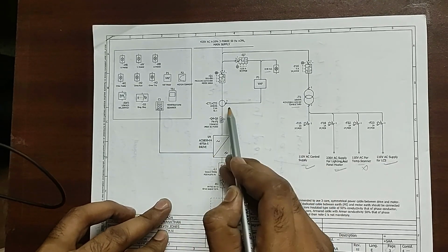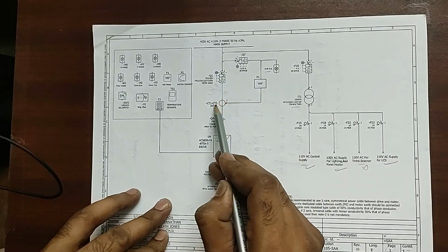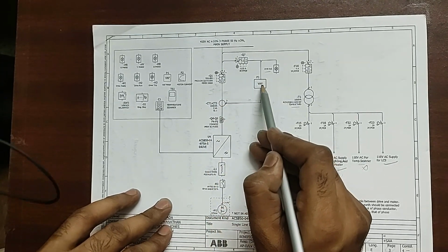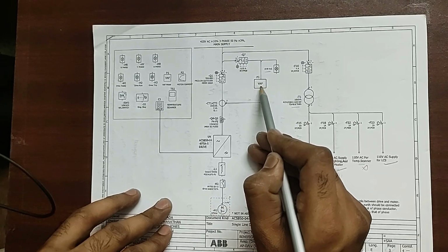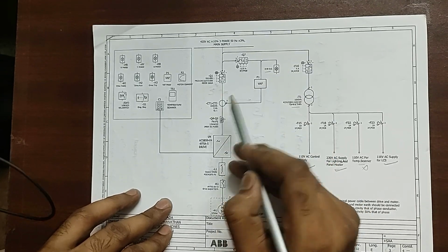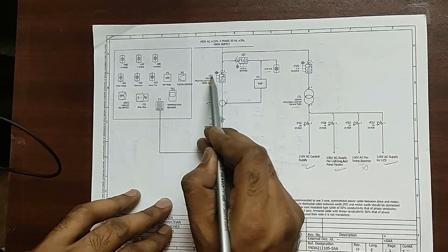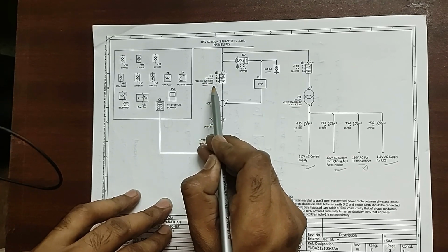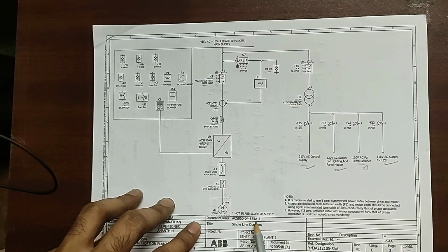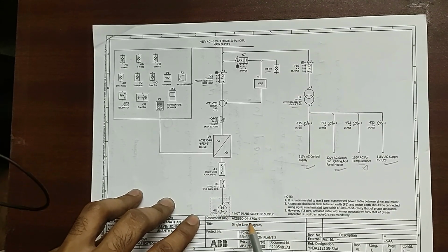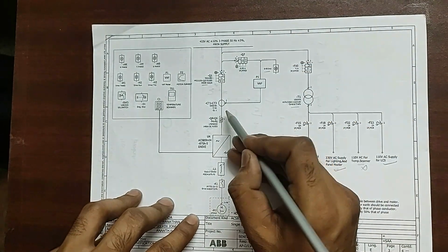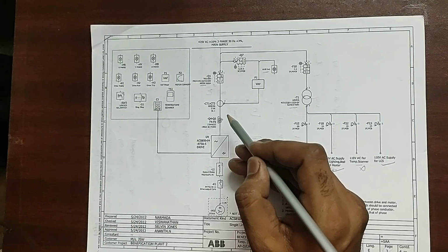It is here. And next, it is connected to CTs. So these are 3 lines, RYB, and it will go and feed the VAF meter. So for current, it will check the ratings from here. We'll see it ahead. And Q1 is very important, that is the main MCCB, molded case circuit breaker, 1000 amps here, because the current is quite high for this particular case, that is 875 amps. So once we switch it on, current will come here. This is the CT for all the 3 lines.